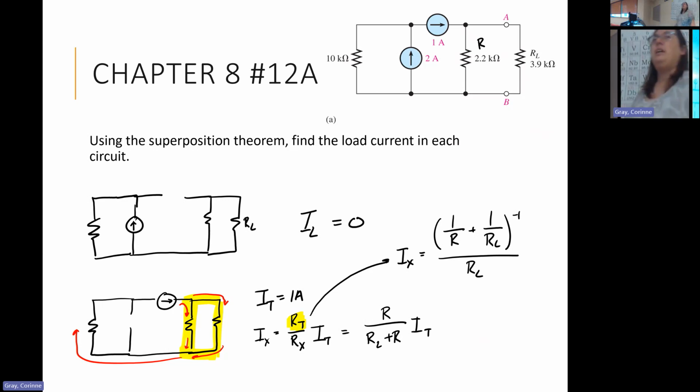So we don't technically have to convert here if we don't want to. It does not hurt you to convert. We'll see in a later example that you do have to convert one way or the other. If all of the resistors are given with the same prefix, it doesn't really matter if you're dividing. If you were to do some multiplication or something, that might be a different case, but here we have resistance divided by resistance, so we do not have to.